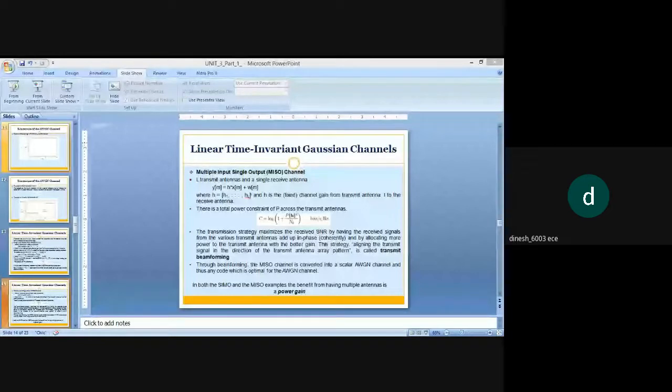So this is your frequency selective fading channel block diagram, where the information is present here. The information bits are coded onto an encoder, and from the encoder it is sent to an OFDM modulator, orthogonal frequency division multiplexing modulation scheme, and each OFDM symbol will lead to a corresponding channel for its usage. So each channel use corresponds to an OFDM block. The coding can be done across different OFDM blocks as well as over different subcarriers. The channel is considered to be a frequency selective channel.